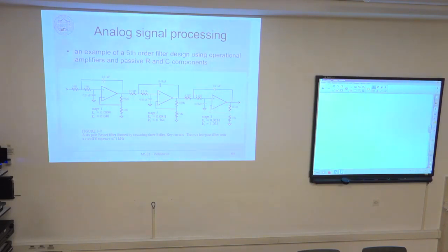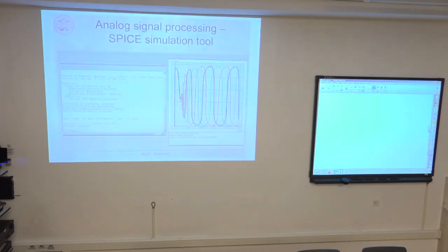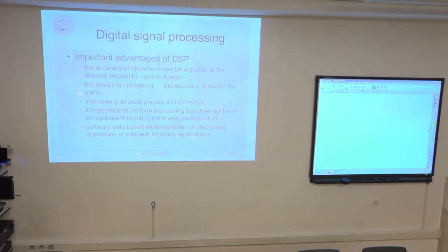The other problem is outside noise, because you might have some kind of additional sources around this device that create electromagnetic interference, and it is then coupled into the circuit, and again it creates some kind of unwanted signals in certain points in the structure. All of this does not happen in digital form, because we have these digital numbers and they do not affect one another. Simply, we don't have this kind of crosstalk problem or noise problem. So that is a big advantage.